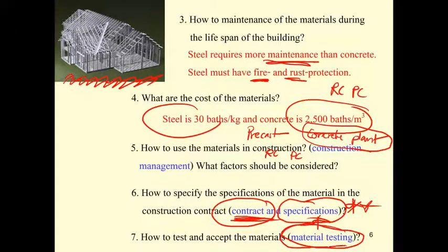For example, if you use FE24 steel following Thai Industrial Standard 119, and then you buy your steel, for every 10 ton you have to collect at least 3 to 5 specimens and send them to the lab. That 10 ton of steel costs 300,000 baht. That's quite a lot of money, right? So when you buy things, you have to have the test for acceptance quality control.